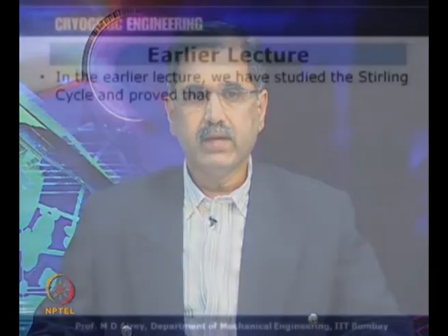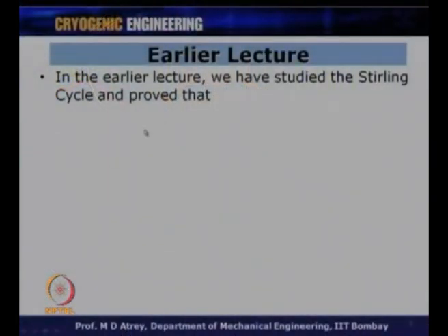So, welcome to the 28th lecture of Cryogenic Engineering under the NPTEL program. In the last lecture, we were talking about Stirling cycle cryocoolers. We studied the Stirling cycle and proved that the COP of the Stirling cycle is equal to the COP of the Carnot cycle. The COP is highest, and it is as high as the COP given by a Carnot cycle working in the